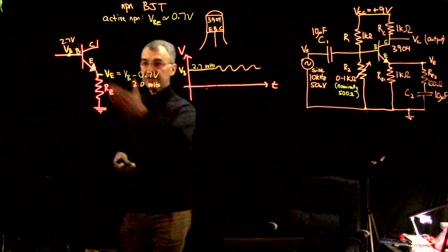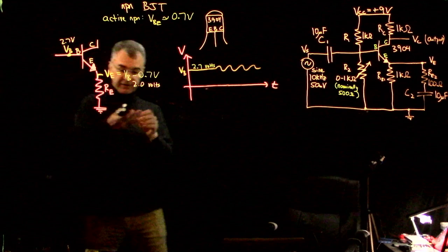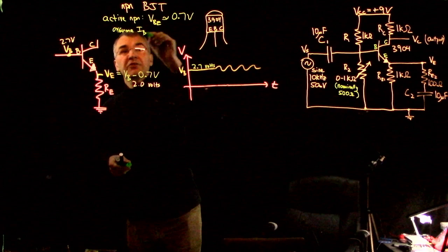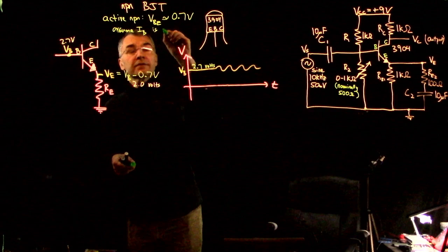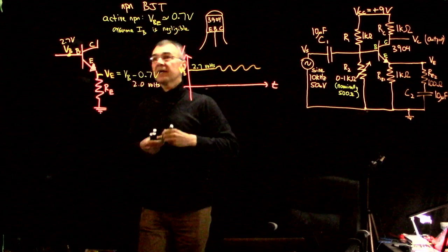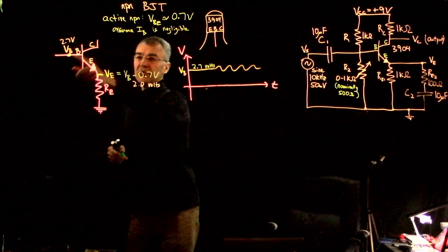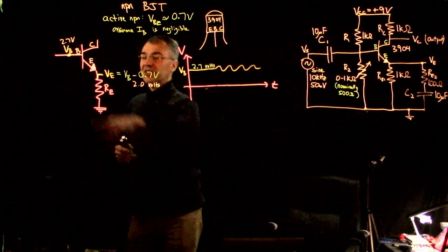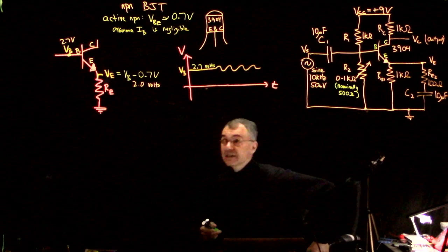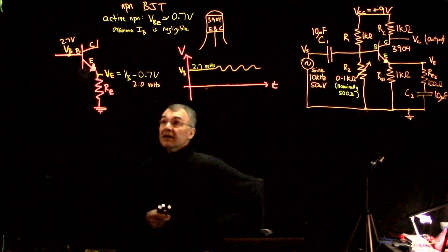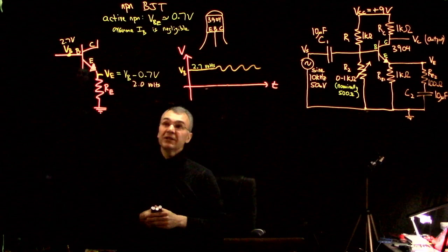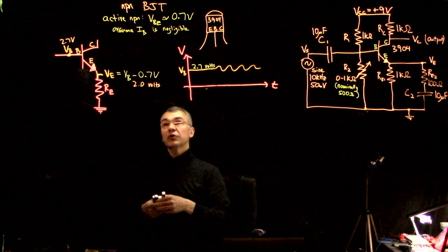And so then we start at the base, and again, we start out assuming that I base is negligible. Actually, I guess that assumption doesn't matter too much here because we don't have a voltage divider network here, but normally we have this biasing network, and then what I base is will affect what V base is. Here, let me get down a little bit out of the way. So then we know what VBE is. It's a diode drop. So now we know what IE is.